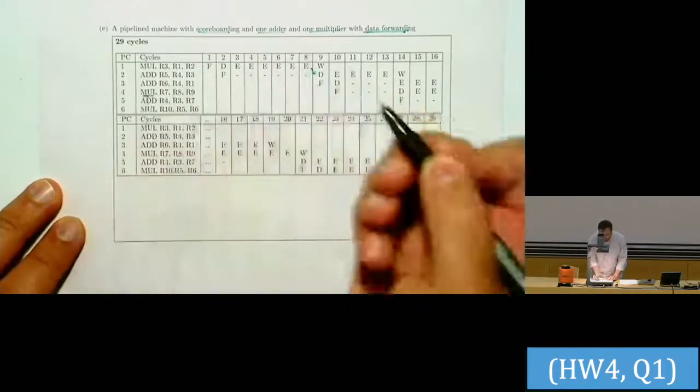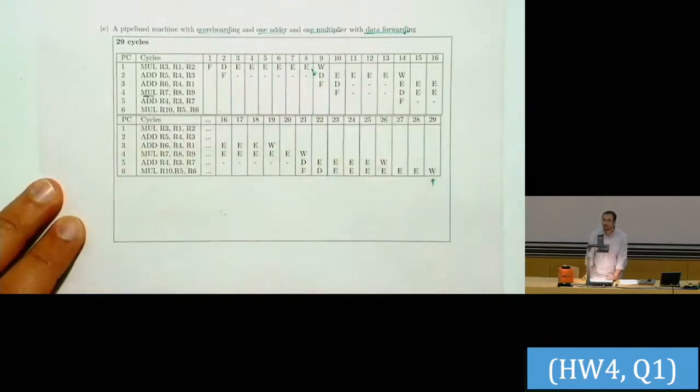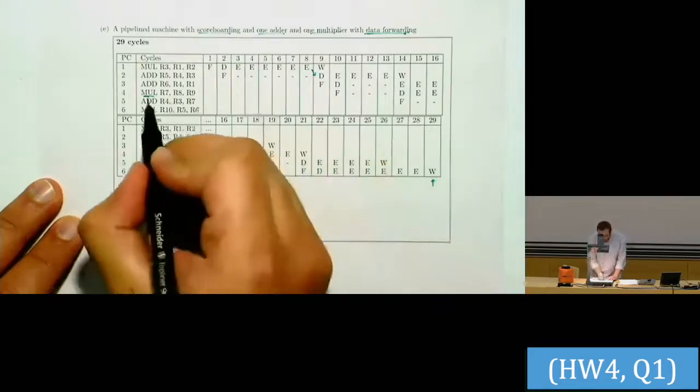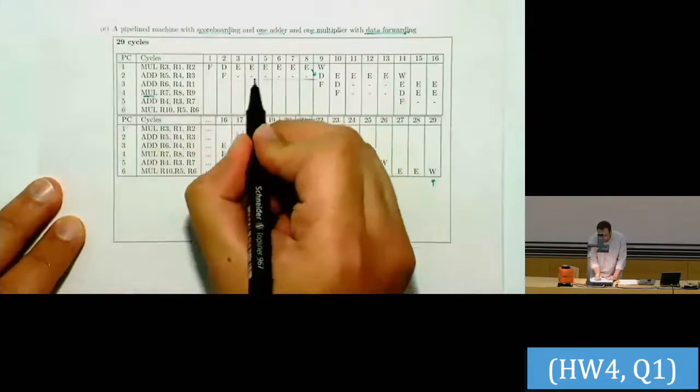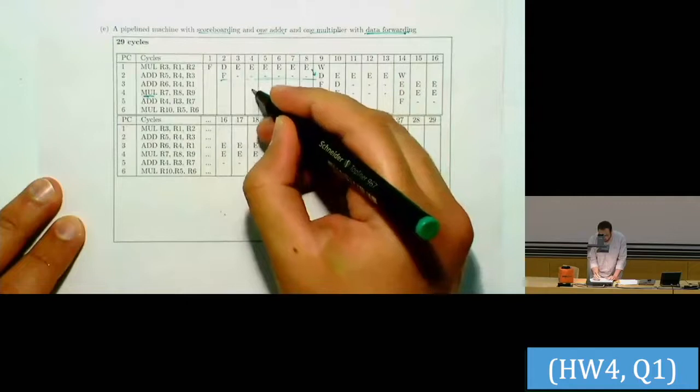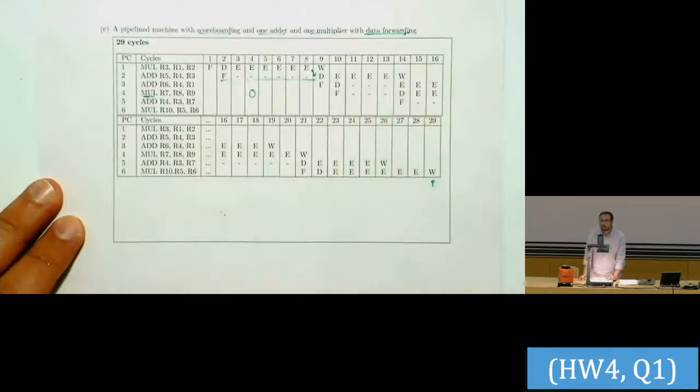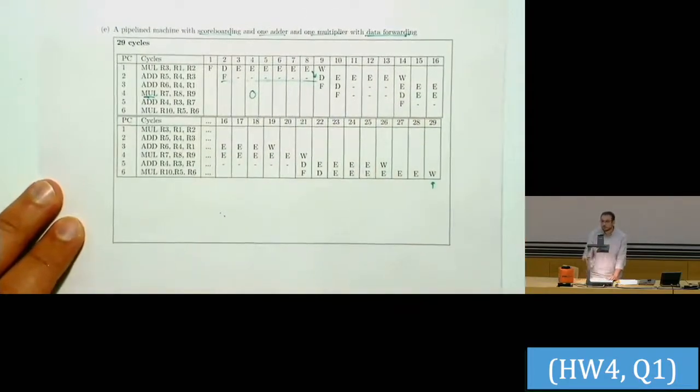So this is, okay, so there's another bottleneck here, right? So you have to fetch and decode these instructions, and you have a bottleneck over there. So the fetch stage of the pipeline is busy with the second instruction still here. So you cannot fetch this. So to avoid it, for example, you can go for fetching multiple instructions at the same time and more complex designs.